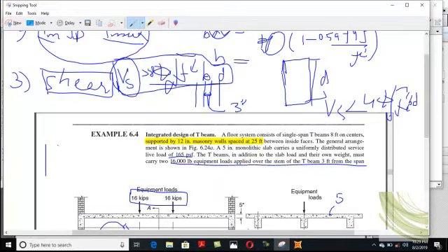If it is the face of support, and this is your shear diagram, this is 64. Your critical shear lies at a distance d, the effective distance d. There is your critical shear VCR. It lies at the distance of d. Now, what is our effective depth?